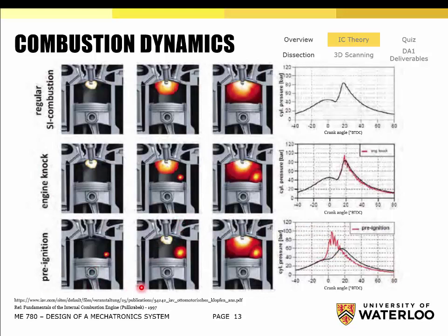The engine knock will occur as everything starts to heat up. You're going to generate a lot of extra pressure, which is not going to do a ton of useful work. That extra pressure will make extra temperature, and it'll start increasing the temperature of the engine and the cylinder walls and the exhaust valve and the intake valve and the spark plug. And then all of these things are just going to cause enough temperature to spontaneously combust the mixture by pre-igniting it in a subsequent cycle a few seconds or a few minutes down the road. So it might start on diesel fuel. It might run for a few seconds. You might start doing some damage, but you can start driving around, and then you'll probably break something a little bit into using it. So I would avoid doing that, yes.